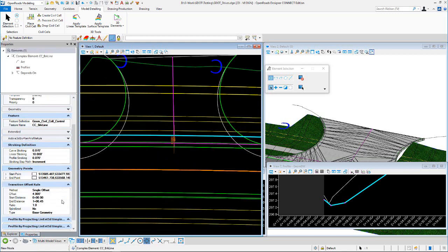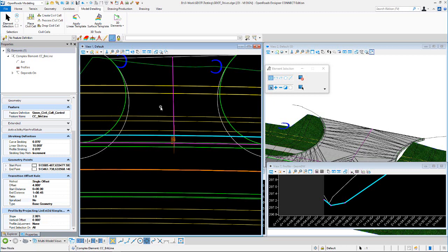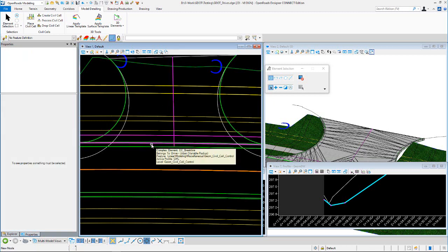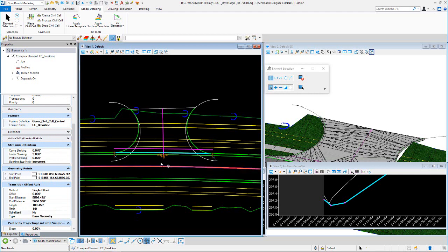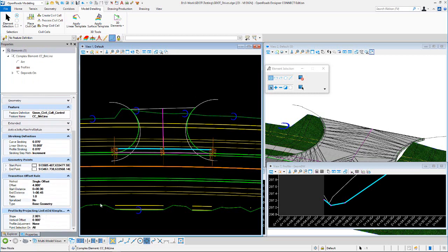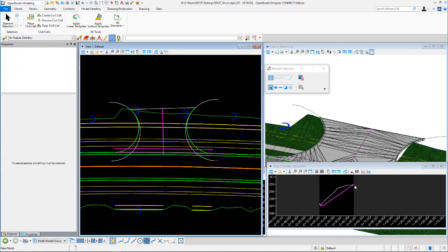And if we look at the slope, it's positive 2% off of this element right here, which is actually that break line there. That's just an offset partial that's right on top of your curb flow line, and that's actually this point right there. So that's really your curb and gutter flow line elevation. And then that other one is, what did we say, 2% or 4% up, 2% up from that. Right, and then basically from there is to tie down to the existing ground.